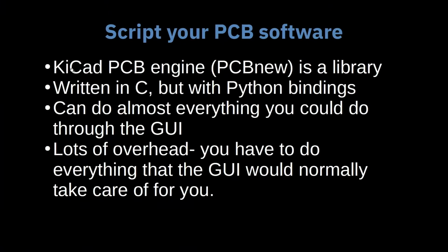So fortunately, KiCad is a pretty awesome tool for doing circuit board design. And it turns out that the engine for the PCB tool for it is pcbnew, and it's a library. So actually, they publish bindings for it. So you could actually just script with it, and you can do anything that you can do in the GUI with a script. And the only issue with it is that it's really designed to power their GUI, which means that anytime you want to open up a project and start something, you have to do 15 things. You have to make an object and then assign something to an object and connect everything. And so you can program it, but it's frustrating.